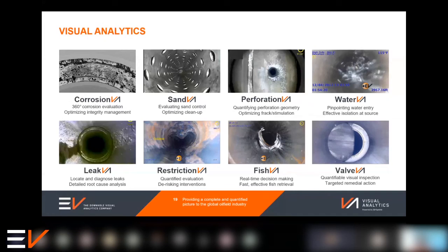You cannot completely displace that fluid. You need to have your weighted brine above us. We can just clear that few feet that we just need to see to get the picture and get back to surface. So several means to do that, and we have quite a number of years of experience and expertise in wellbore cleanup.